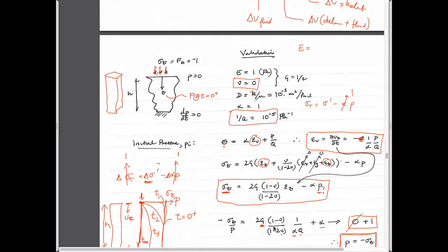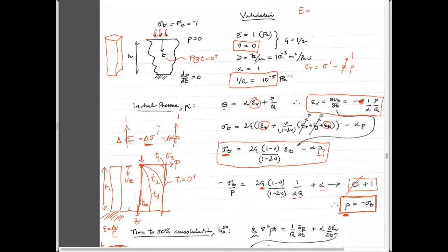And so hopefully you followed that. Hopefully it wasn't too convoluted. But the basic principle is that you want to be able to apply some very simple conditions that you think are realistic enough to exercise different parts of the model. Exercising the magnitude of the fluid pressure you might generate, which is kind of the essence of poroelasticity, and exercising the time it might take to dissipate those fluid pressures, which is the second part of what we talked about.